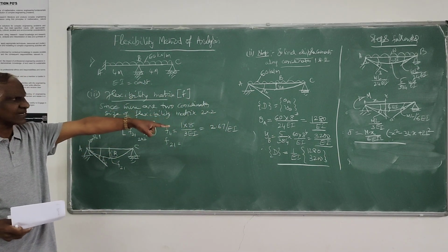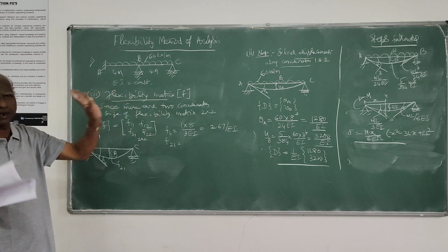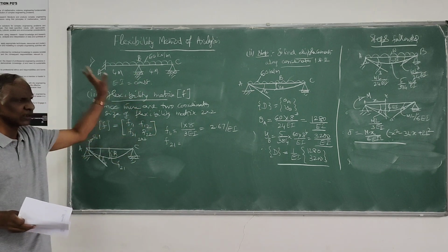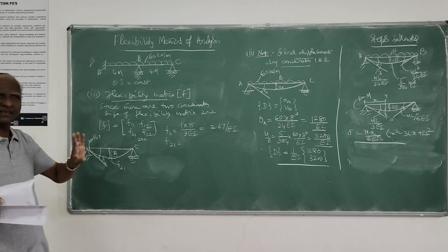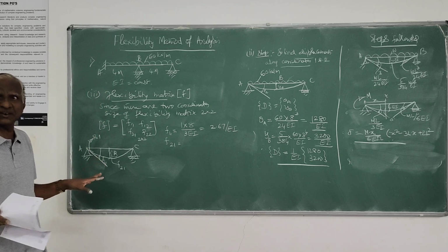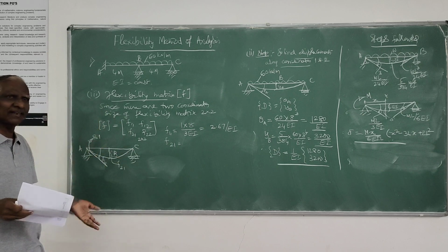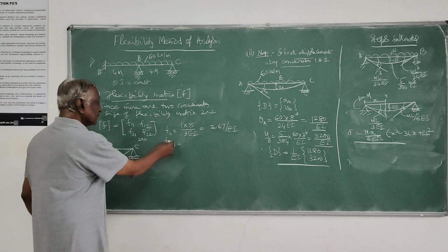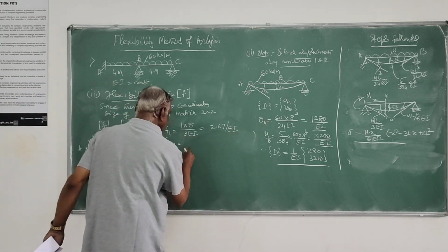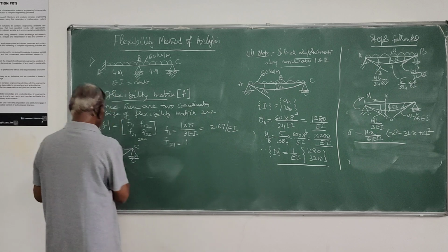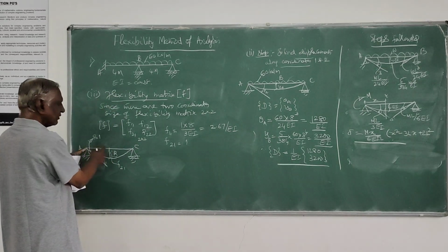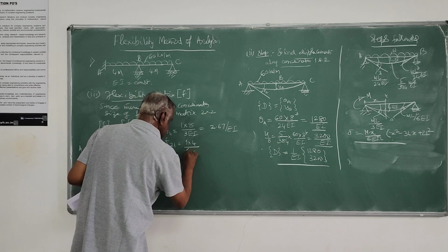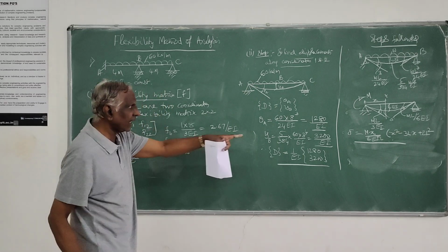Displacement at any distance x from the left hand is given. That formula you have to remember, at least for the standard cases, so that you can work the problem very easily, rather than resorting to the unit load method. So for this F21, M is 1, x is this distance, that is 4 meters. I need 1 into 4 divided by 6EIL.